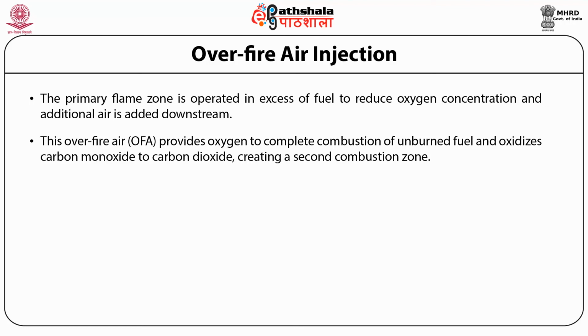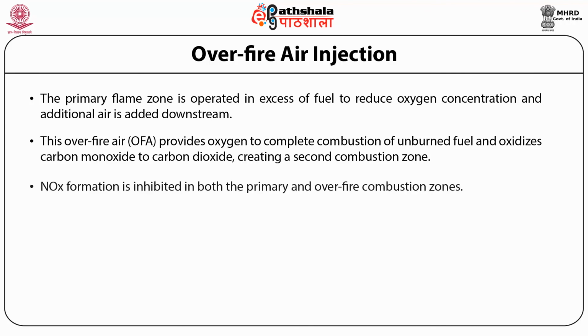Because there is so little fuel in this overfire zone, the peak temperature is low. Thus, NOx formation is inhibited in both the primary and overfire combustion zones. This technique results in air staging.